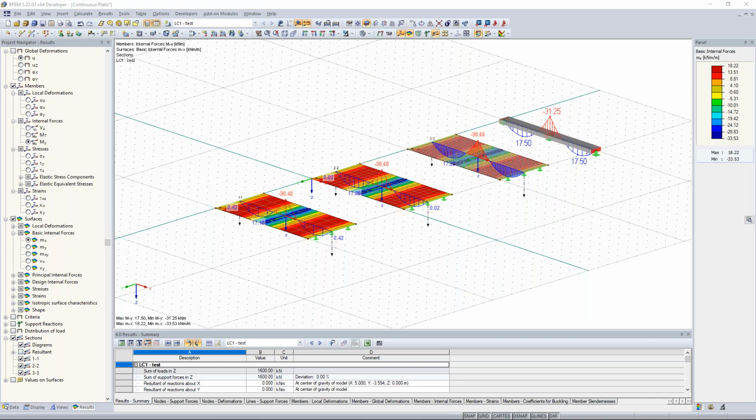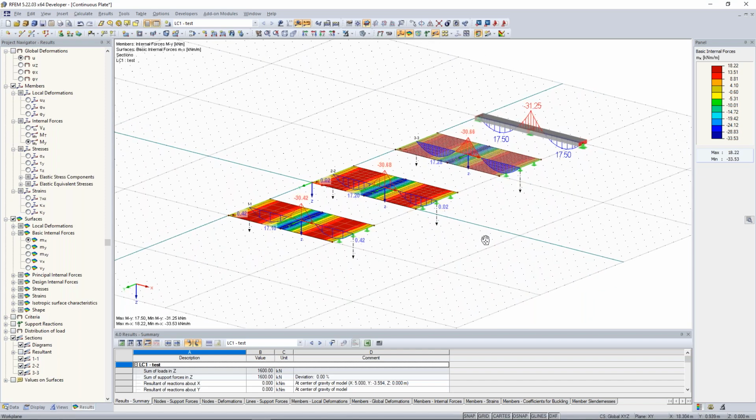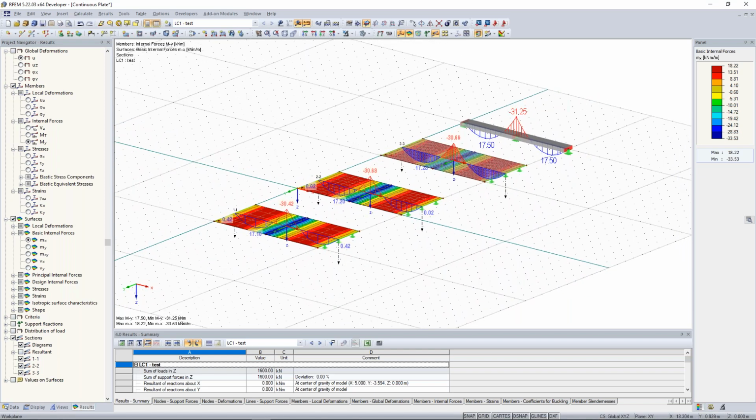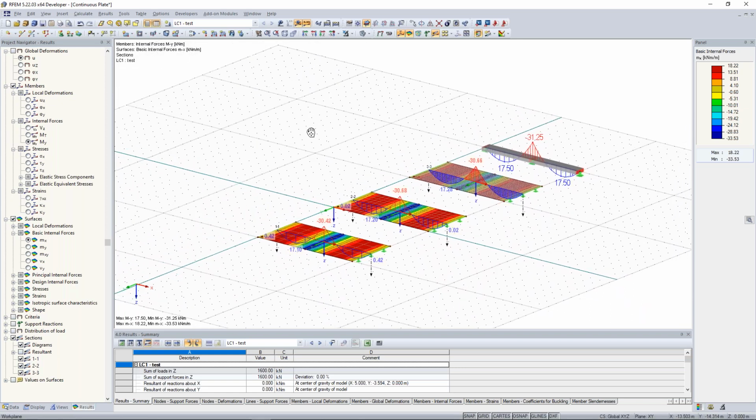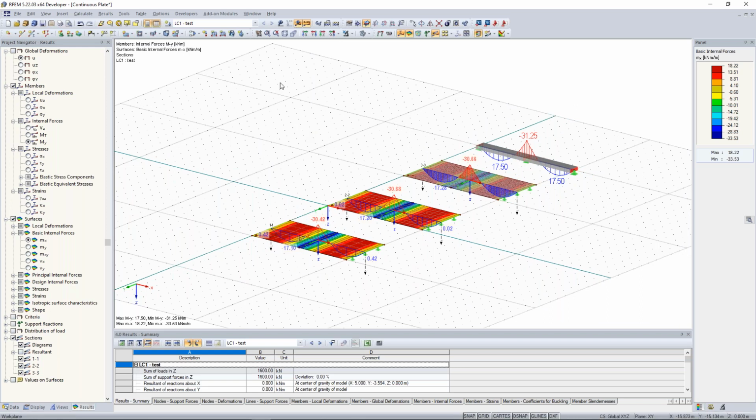We'll do it. Okay, we got one more question about the division of members, because the question was about the menu that shows up if you click, for example, divide member, and then divide member in n intermediate nodes. In the new menu that pops up, there is an option to click on divide line by new intermediate nodes or place new nodes on the line without dividing it. Okay, I understand. We can look it up.